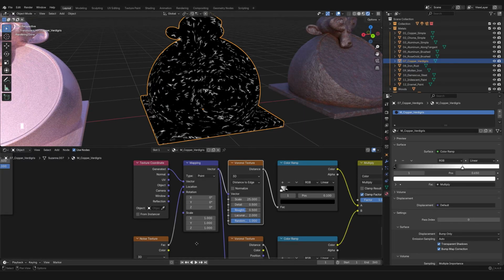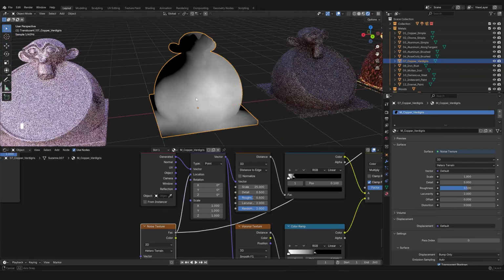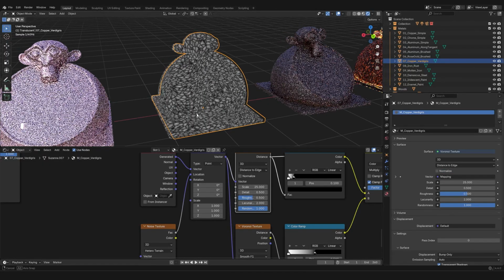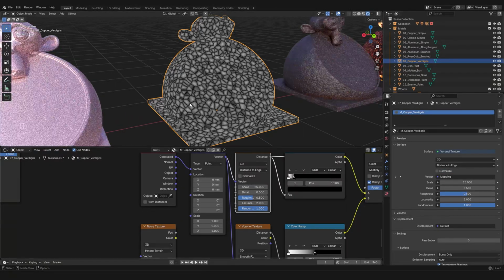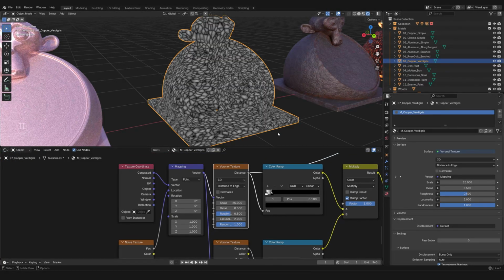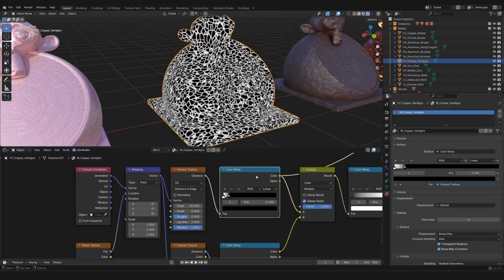the object, okay? We have a noise texture that as is doesn't make any sense, but when plugged into the location, fundamentally brings about this kind of distortion. So the noise texture, when plugged into the location, helps distort this noise further. So we have a sort of inception moment where there is a noise distorting a noise, right? And then the result is passed through a color ramp to compress it.